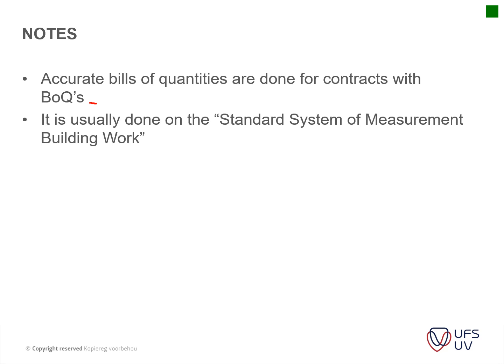It is usually done on the standard system of measurement work. Very important, because now it becomes a legal thing. If, for instance, I say excavations of your strip footing, does it include carting away of the excess material that's not going to be used again, or is the material just spread over the site, or what do you do with that excess material?